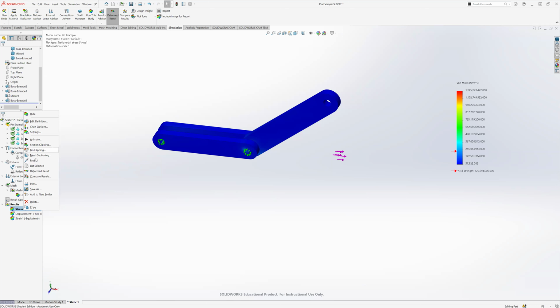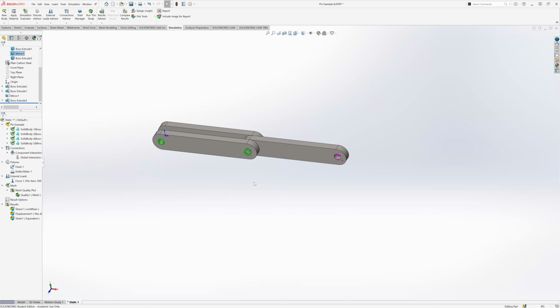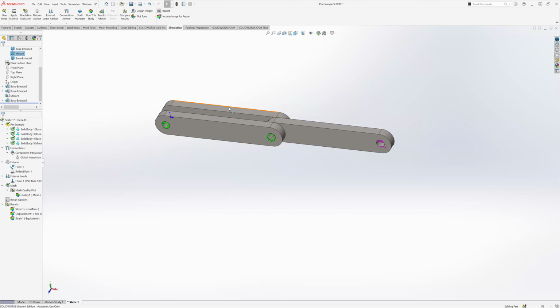So let's go and hide this and keep constraining it. And this is where constraints can obviously be very important. There's a couple things we can do. I don't need to put any roller sliders here. I actually made a mistake earlier saying you need a roller slider here. You do not, because of this fixed constraint here. This cannot rotate, so there's no need to put a roller slider here. We can put a roller slider here. That's probably about the simplest way of doing it.